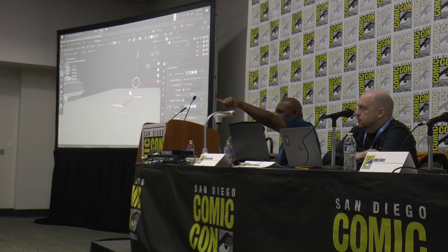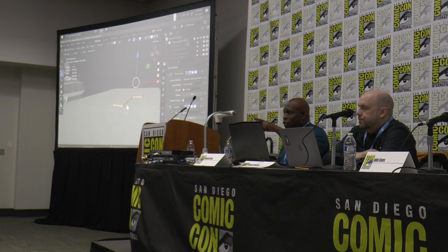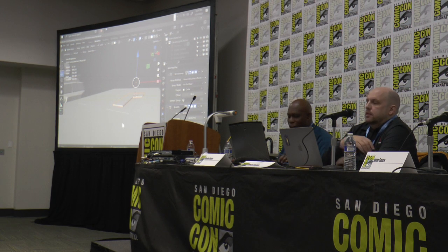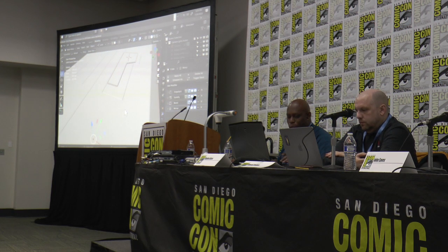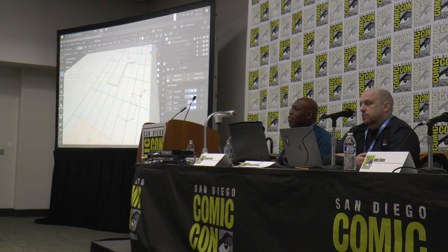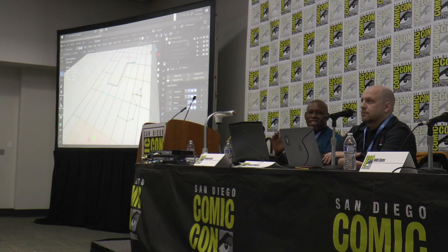Yes, right back there. I'm wondering how you might handle bevel lines for a shape that might not necessarily follow the topology of your model. Okay, I'll show you that real quick, and then we're going to go over to Nikolai. All right, so you use the slice tool. If I go inside the ship real quick, edit mode, hit the K key for the slice tool, and you can start to slice stuff however you want. Thank you. You're welcome. All right, Nikolai's next.